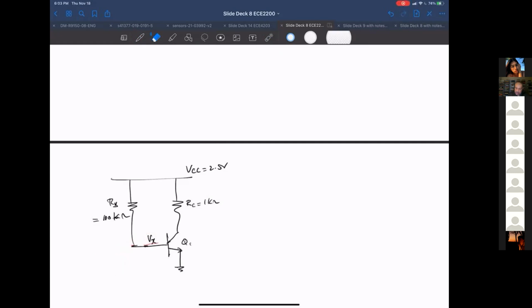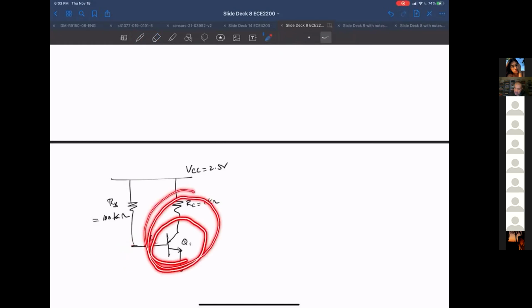So these are the values I select. The idea is, again, that with this transistor on, there's going to be a certain collector current running through this. That collector current is going to have a certain base current, and I can use that base current to drop just the right voltage across a resistor from VCC to get this to the right voltage, so it has the right collector current.